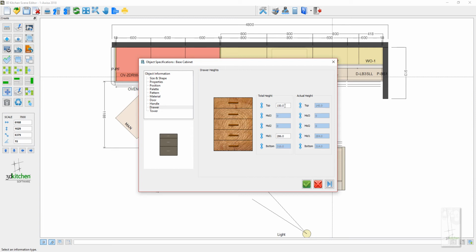Now, what's also modified in here is that these are permanently set to 1 decimal point. So when there are fractions there, you don't have to set the entire program to do that. They will automatically display the correct value correct to 1/10 of a millimeter. This is mostly of importance to those of you who are going out to CNC machines, so that you get a very accurate size for cutting on your CNC.